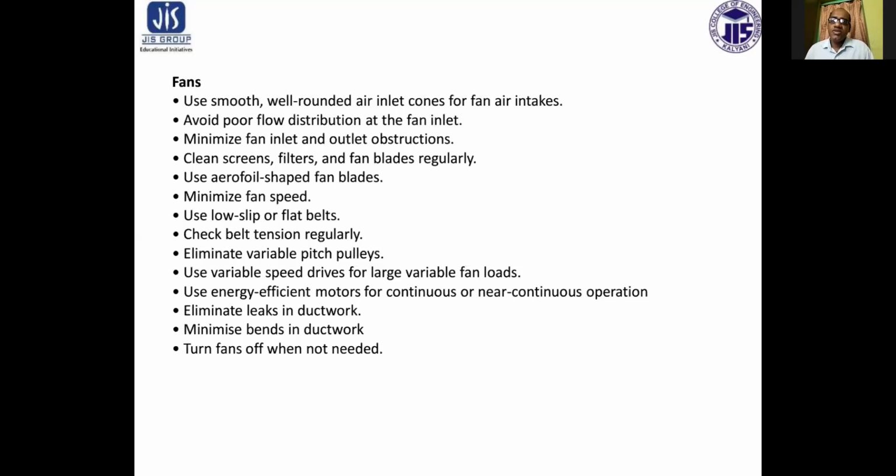Fans. Use smooth, well-rounded air inlet cones for air intakes. Avoid poor flow distribution at the fan inlet. Minimize fan inlet and outlet obstructions. Clean screens, filters, blades regularly.